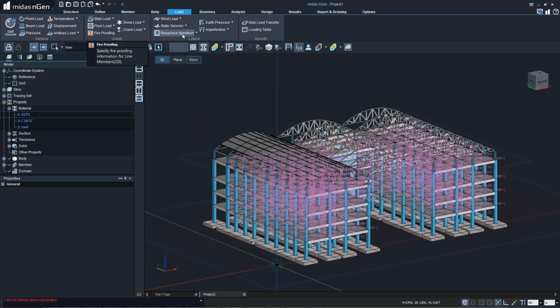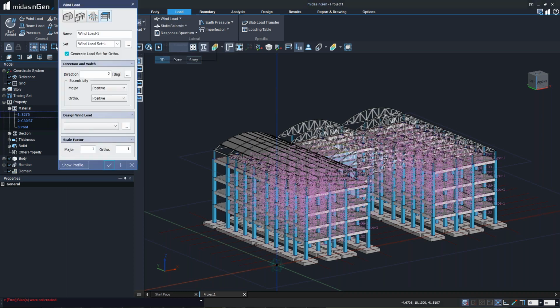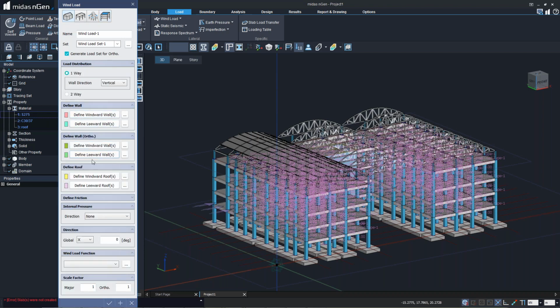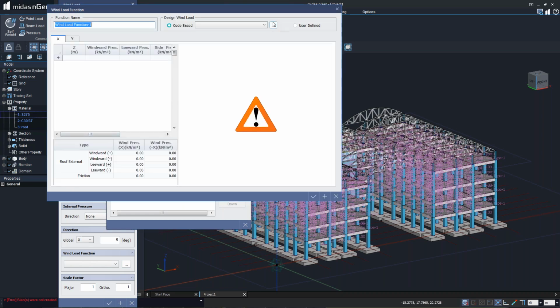Okay, now we will move ahead to the next part, that is automatic calculation of wind. So there is wind load option available. You can have it for enclosed area, open areas, equipment type, or story based. So when it comes to an RC structure, you can use simply the story based command. And in case of the equipment, or rather over here we have got steel sheds. So in case of steel sheds, you can use this enclosed area option as well, wherein you can use the curved roof calculations. So you can select all the windward walls, leeward walls, roof walls, and so on. So that's the information which can be again automatically calculated by the program.